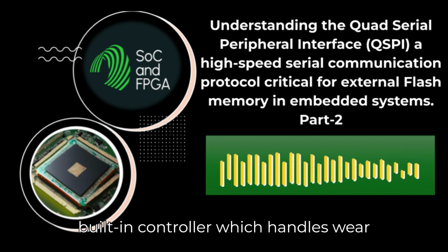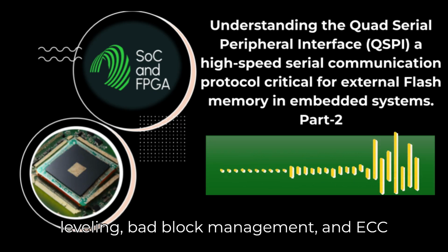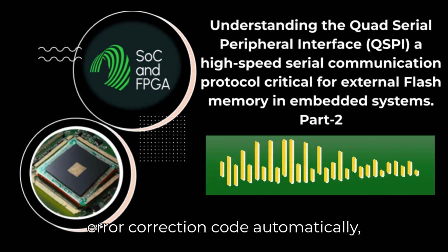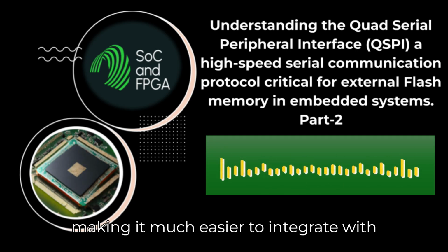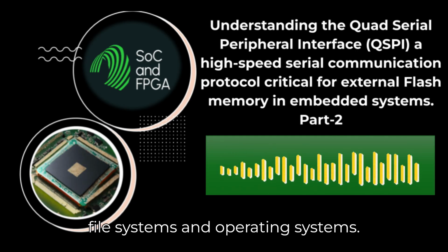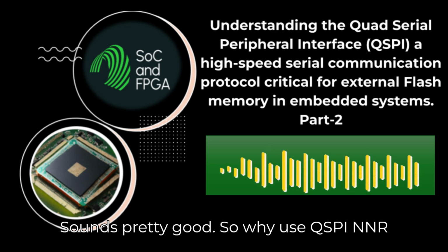It also has that built-in controller which handles wear leveling, bad block management, and ECC (error correction code) automatically, making it much easier to integrate with file systems and operating systems. Sounds pretty good. So why use QSPI NOR then?